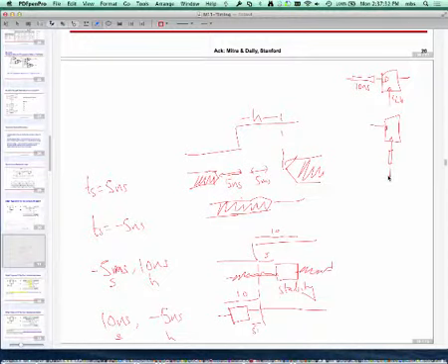So an ideal flip-flop will have a positive setup time and a positive hold time around the clock edge. But because wires may have different amounts of delay, or there might be a buffer or inverter in there, what you often end up with is that the setup time may be negative or the hold time may be negative. But it's not as if you're suddenly doing time travel as a result. That's not happening.